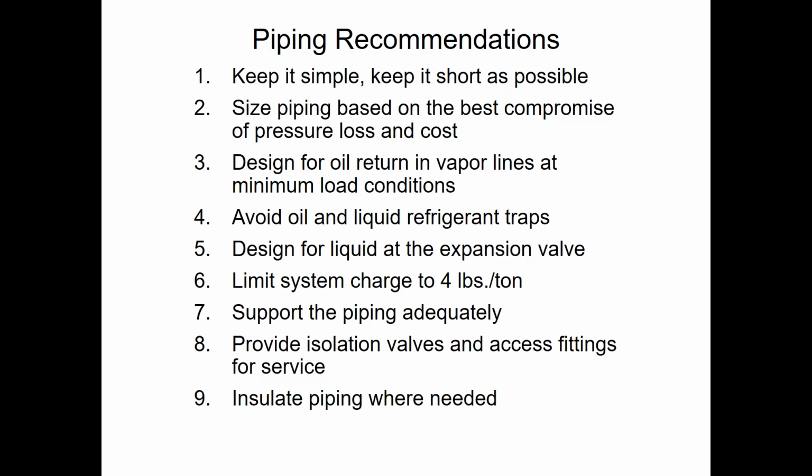And how much does that cost us in pressure drop and performance issues? So when you get into that balance, when there are a couple pipe sizes to use, always keep your capacity and your performance in mind, as well as cost. Of course, we always design for oil return in the vapor lines, meaning your suction and your hot gas lines. Fortunately, in the liquid line, we don't worry about oil return because oil is quite happy entraining with the liquid refrigerant. It's the vapor state that we run into trouble with entrainment.